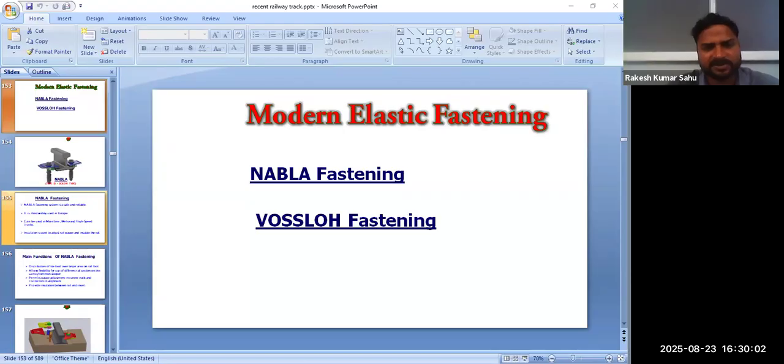Here is a ballast profile of long welded rail, single rail line on pre-stressed concrete sleeper. These are A, B, C, D parameters. And here the quantity used per meter, 2.58 in straight track and 2.61 in running track. This one, other than for LWR track.